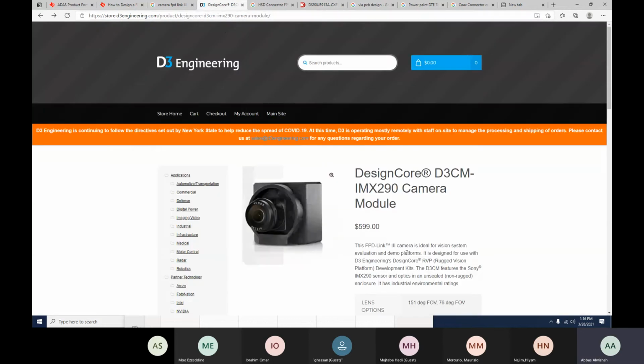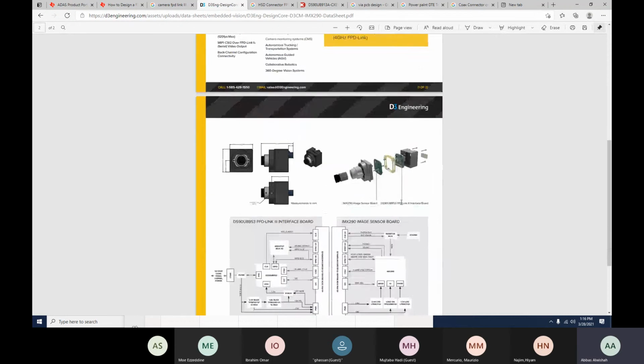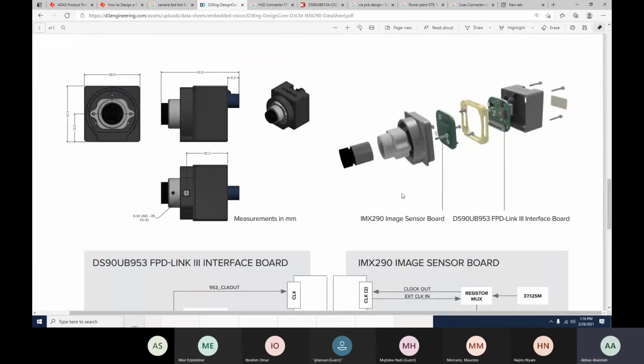And the same thing here when you're designing the camera, mechanically you want to ensure that everything is stacked up good. They probably have this in a metal housing, I would say, because it can dissipate the heat, one, and two, as you touch it, it's already grounded. It's referenced back to ground, the housing.